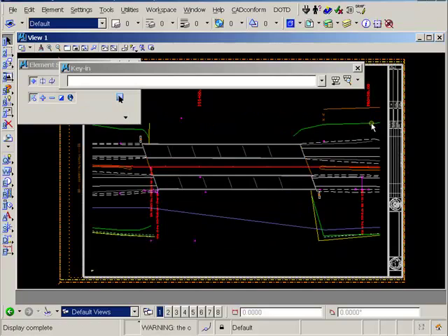I will use the Fit View command again to fit the final graphics in my current view, and then I can close the reference file dialog. If you ever need to change the display extents of the survey in the site plan, all you have to do is reposition the border reference file and redo the clip boundary for the survey reference file.